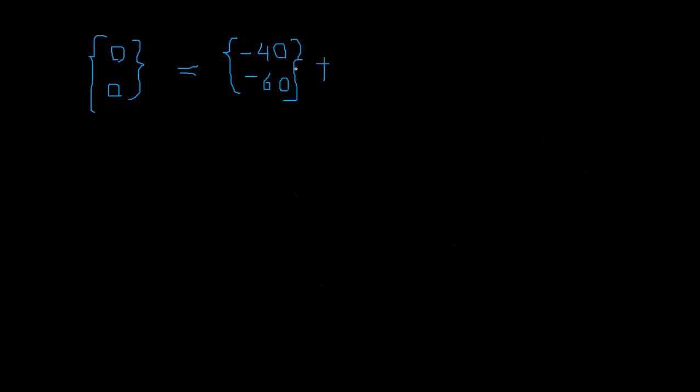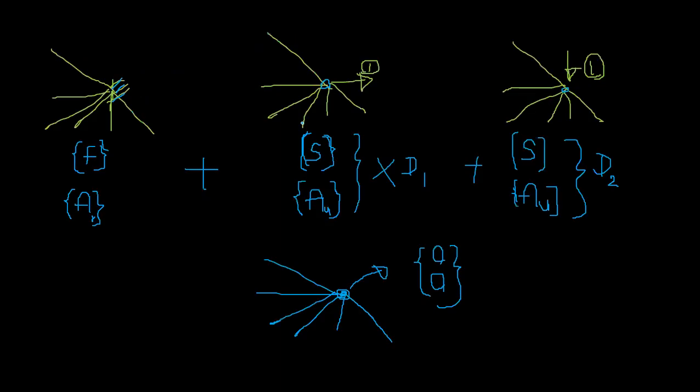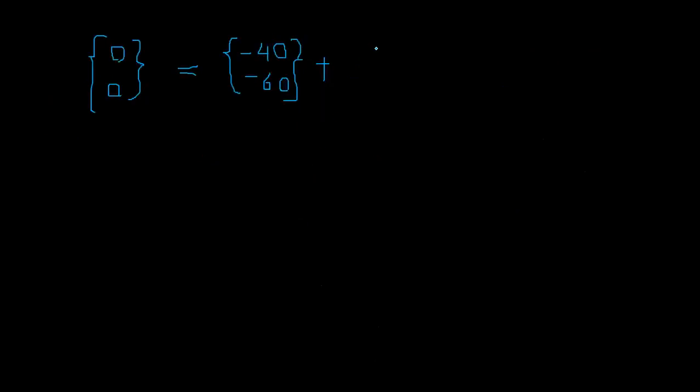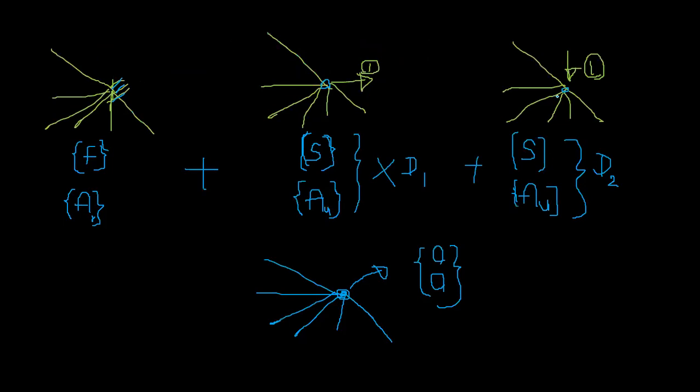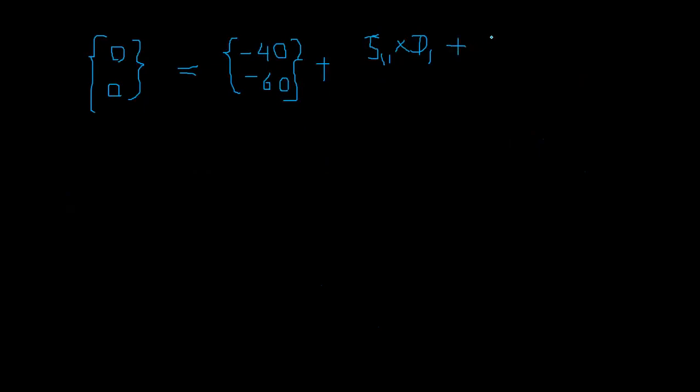So you took it as minus 40, and so this is the restraint forces, you remember? And then you apply each force and calculate the unit displacement and calculate each force. That means the stiffness. And that is the S11 into the real displacement. And here it is S12, this is the second direction, S12 into D2.